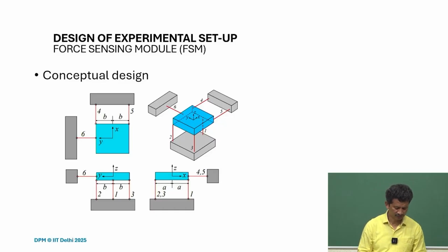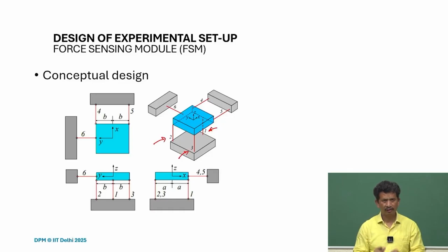So for instance, here you can see that at the bottom we have 1, 2 and 3, so 3 vertical rods. Later of course we converted them into a flexure design or used wire flexures there. But to start with, you can think of the constraint line approach.